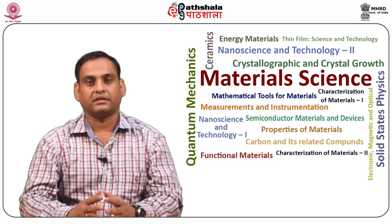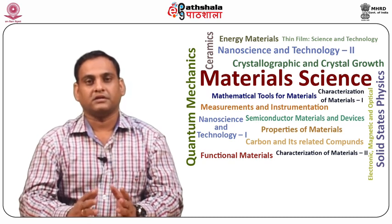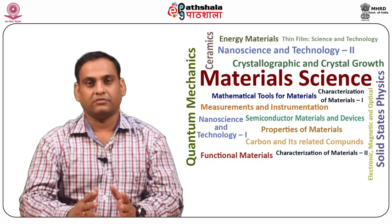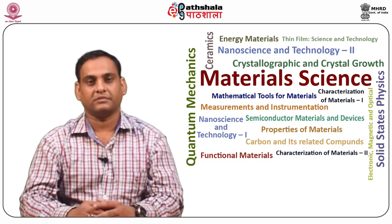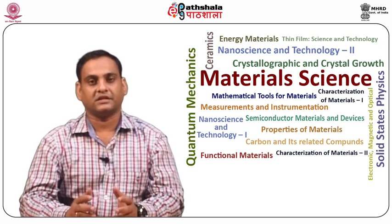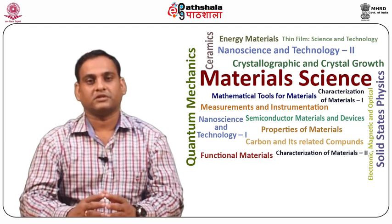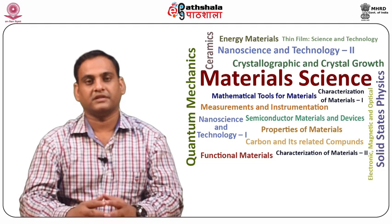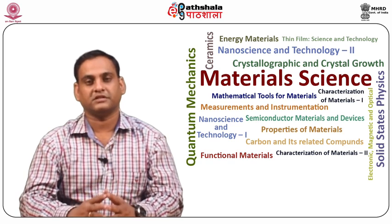Recently, a technique has been developed to produce lamination with greater than 6 weight% of silicon by a silicon SiCl4 chemical vapor deposition treatment to enrich the lamination with silicon after forming the laminations. Typically, most electrical steels will contain between 3 to 4 weight% of silicon. For transformer applications, the flux lies predominantly in the length of the laminations, and therefore it is desirable to enhance the permeability in this direction.